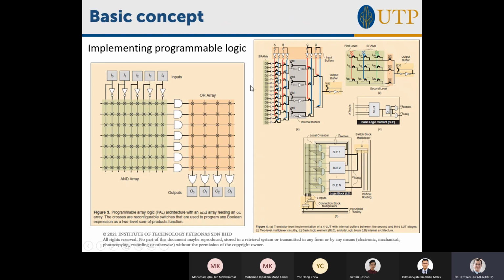The static RAM is setting, turn this on, turn this off, and all that. This is not changing while the circuit is operating. It is configuring which path the logic will take. These wires, this routing, are not changing when the circuit is operating. It's already fixed in that static RAM. What is changing is only these input pins, and you get outputs based on whatever the inputs are.